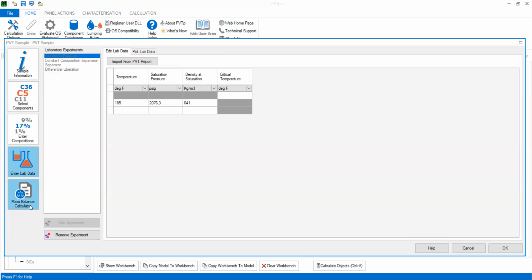All right, a mass balance can be conducted to assess whether the measured fluid properties are actually consistent. The mass of a unit volume of oil and the associated gas is calculated at both surface and reservoir conditions. This can result in one of three scenarios. The first possibility is that surface and reservoir mass are consistent.